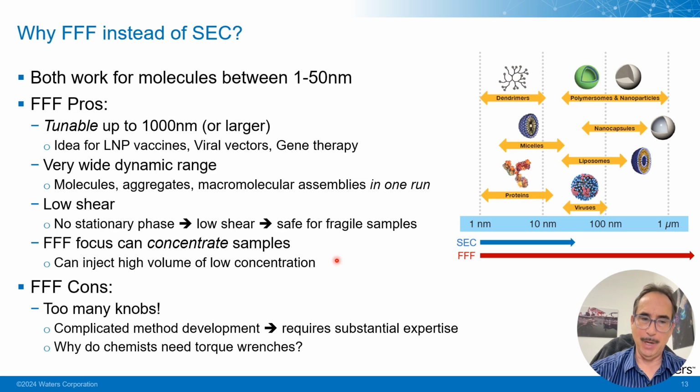And the other nice thing about this is it's relatively minimal sample prep, because if there's a fairly large particle, it's going to feel a very large force and a very low diffusion, and it'll slam down onto the membrane, and it'll essentially stay there until the very end, where you turn off the cross flow and then let it elute. So minimal sample prep in terms of pre-filtering your sample.